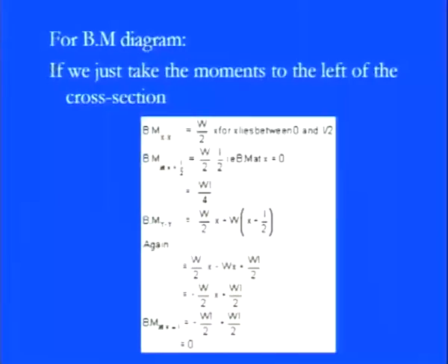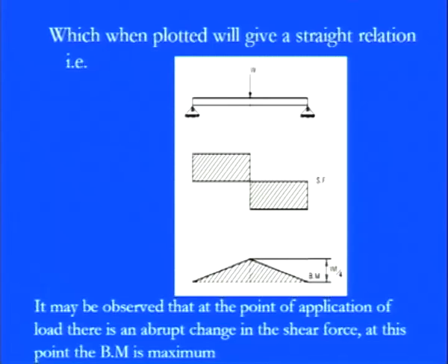So, we saw the effect on the shear force, but here the effect on the bending moment is that we have 0 bending moment at the two extreme corners where the pin joints are, and we have the maximum bending moment, with magnitude WL by 4, at the middle portion where the point load is acting. Okay, so if we want to draw that, then we have this shear force, and now this is the bending moment.